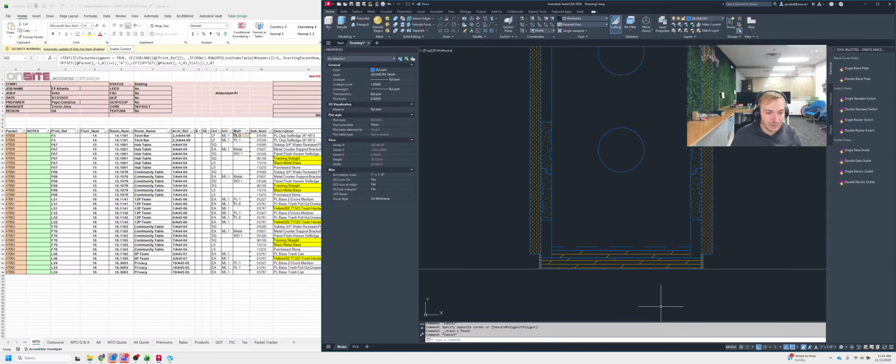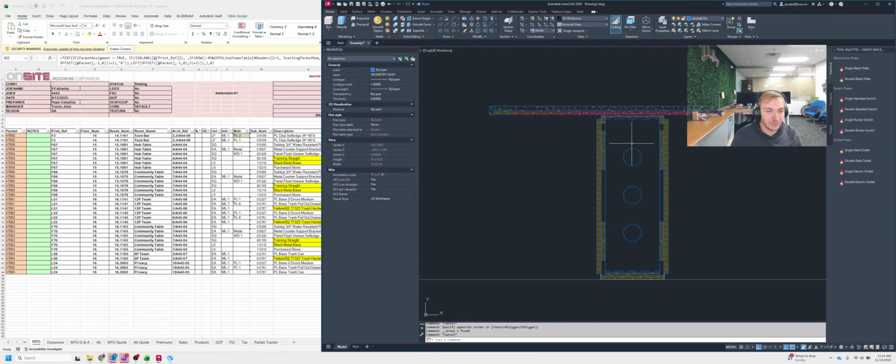And one important thing to note too is that that locator plate does actually span all the way from left to right of not only the rib, but any die wall components that are there. So right now we got cleats on both sides, and this pad is going all the way to the front of that cleat on both sides. All right, so quick refresher on die walls. And then of course we already talked about this, but you have your wire chase holes that run through here. So those are all placed right there and they'll be cut out before this gets out to the field.